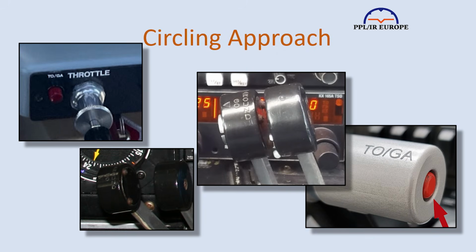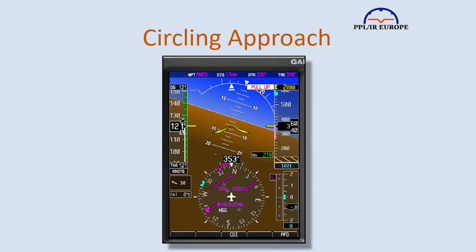If you do need to go around, many autopilots have a toga button giving an immediate straight ahead and climb instruction, which is very valuable as you reorientate yourself and are cleaning up the airframe. Or, of course, you just use raw data and keep a very careful scan going of bank angle, heading and altitude. If you have bugs, I strongly suggest using them. Obviously, this is going to detract from your focus outside the aircraft, which may be reduced to glances. So, no correct answer, but my choice would be flight director in heading and alt until you start the continuous aspect turn to final, then switch it off and look outside, just glancing inside for airspeed.